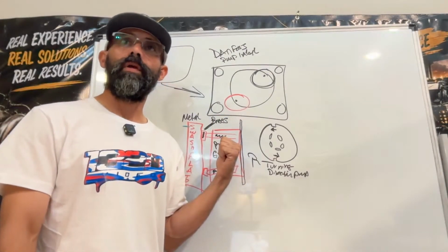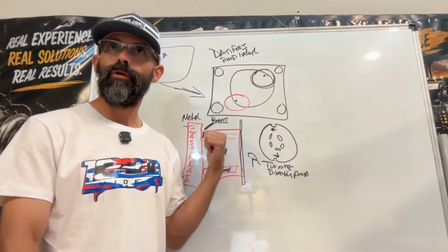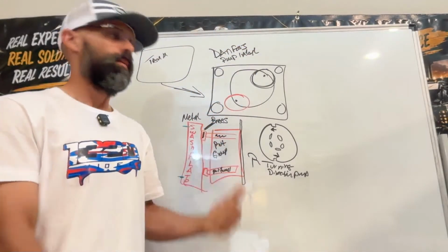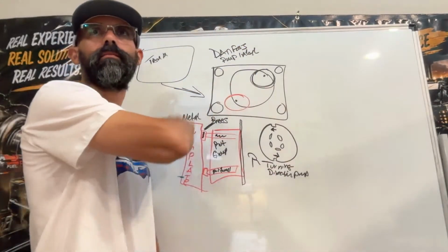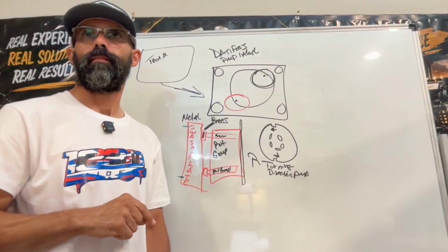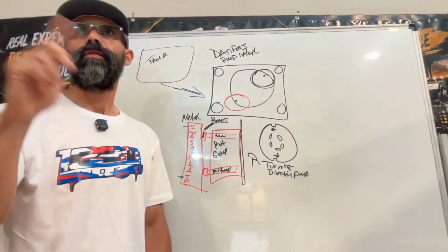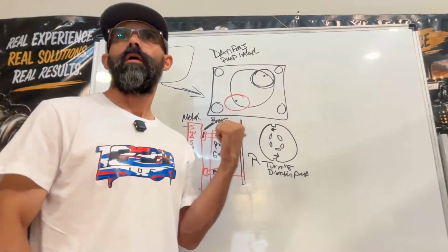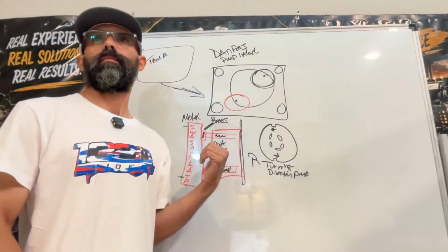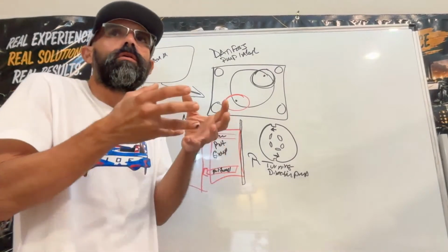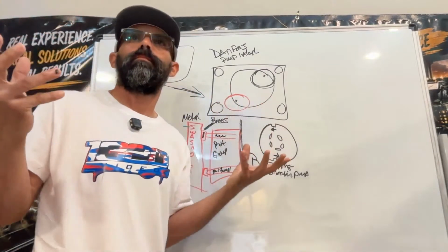If it was lack of lubrication or overheating, you're going to see it right away, because you're going to see heat marks on some of the components. You're going to see if it was water intrusion because you're going to see rust and traces of water right away by opening a small section of the pump. Oh yeah, this is what broke.